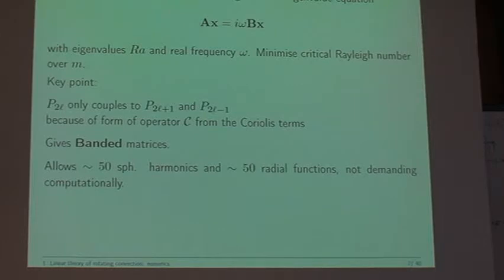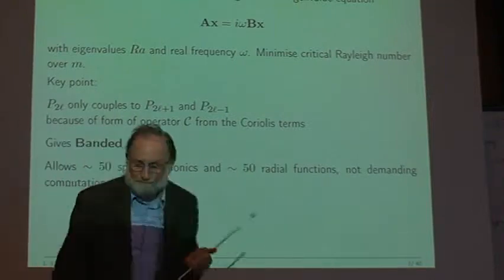In more general circumstances, having got that matrix, I basically reduce that matrix using the boundary conditions, so that I have extra variables. So instead of expanding from 1 to n, I expand, say, from 1 up to n plus 4, and then I get from n plus 4 down to n using those boundary conditions. And then I get what I call a reduced matrix, and then I apply this reduced matrix. That, of course, isn't a huge amount of work because there are only a finite number of these boundary conditions, so it doesn't slow the thing down all that significantly.